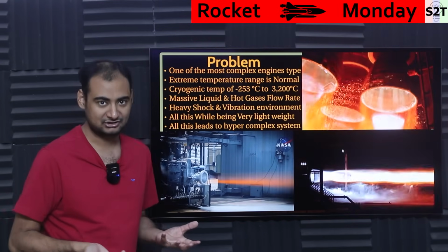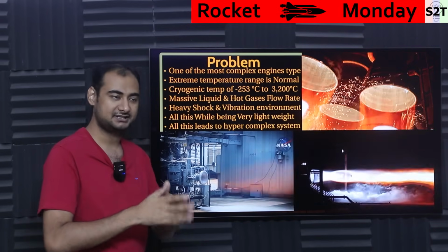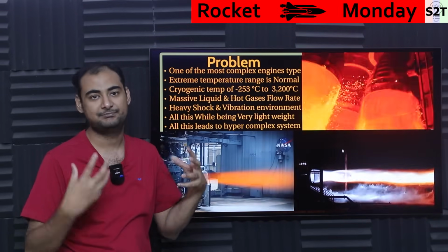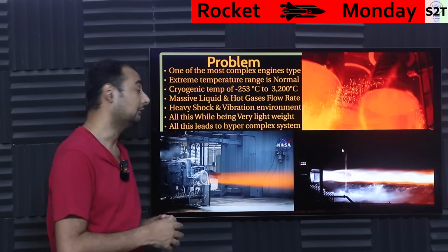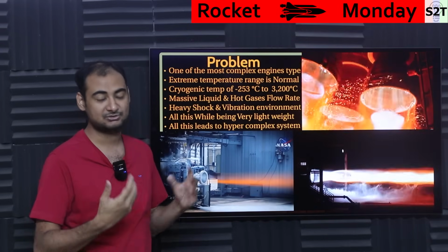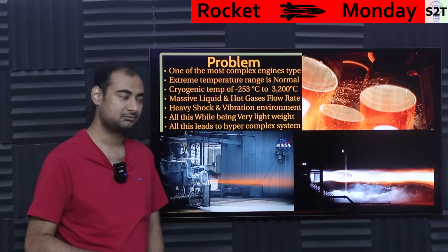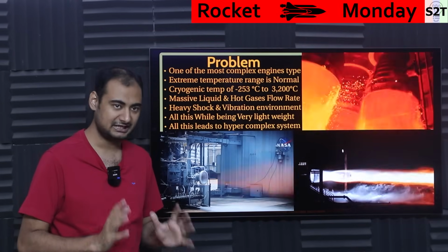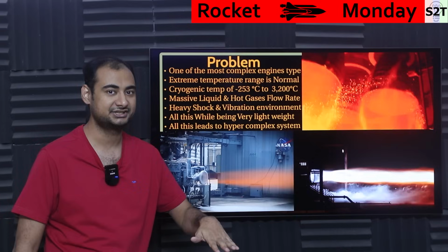And then, because we are talking about combustion, it is not a smooth event. It's not like everything is nice. It has some noise to it. Now that noise in this sort of scenario becomes a very bad noise. It creates shocks, vibration, pogo oscillation, this and that. Oh, and let's not even forget about fighting against the atmosphere. Again, the atmosphere will have different pockets, so that will create vibrations. And not to mention max Q, it puts an extra amount of oomph on you. So you have to be damn sure that you can handle all of this. Basically shocks, vibration, environment, you have to be like, I do not care.